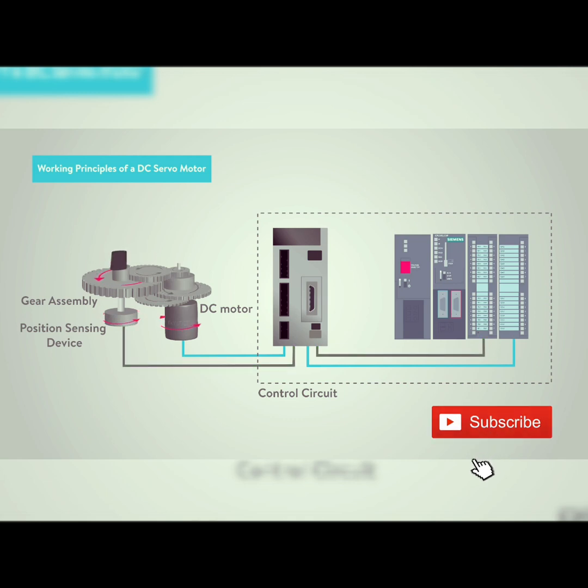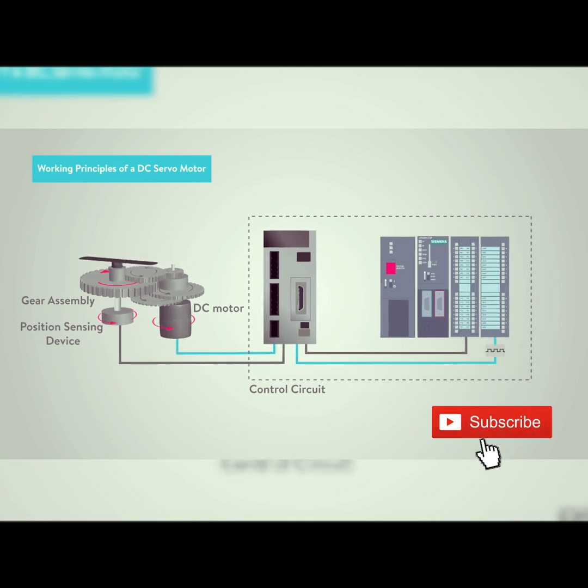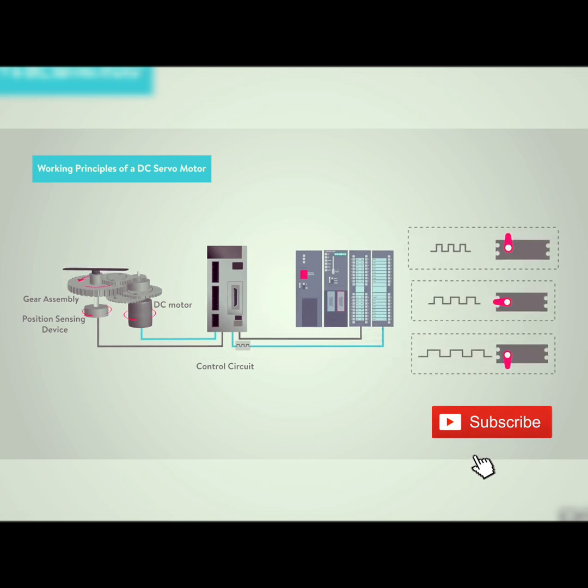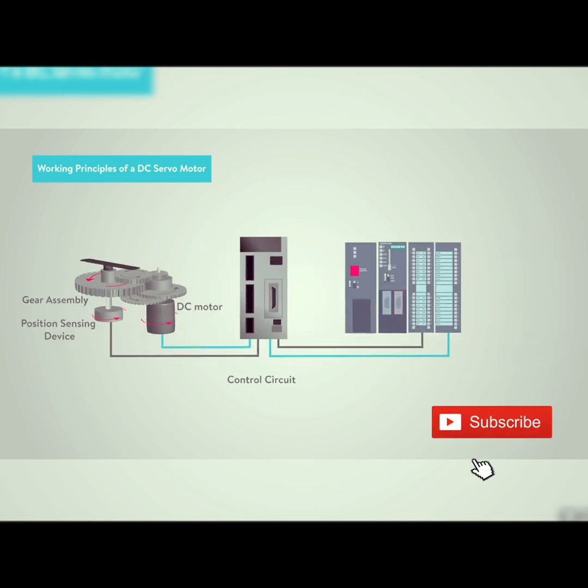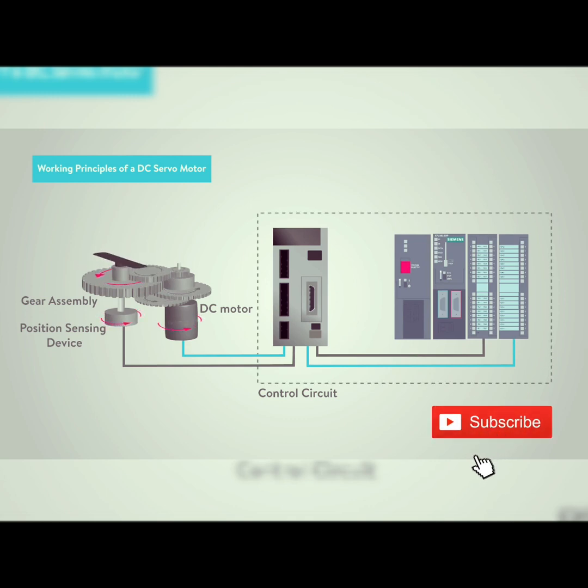to the error amplifier. In some circuits, a control pulse is used to produce a DC reference voltage corresponding to the desired position or speed of the motor, and it is applied to a pulse width voltage converter. The length of the pulse decides the voltage applied at the error amplifier as a desired voltage to produce the desired speed or position. For digital control, a PLC or other motion controller is used for generating the pulses in terms of duty cycles to produce more accurate control.